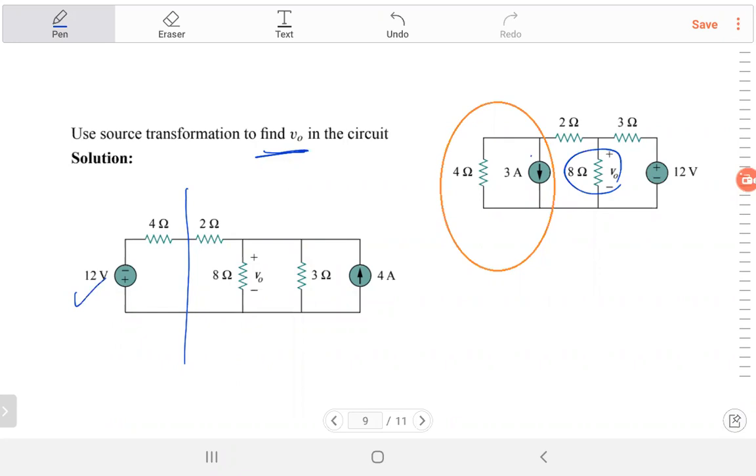The simplification that I did here. What's the advantage? Where are you starting? That's the starting circuit, given like that. Then I take this current source in parallel with the resistance and convert it to a voltage source with the resistance. So this red bar comes here. Convert it to this one.